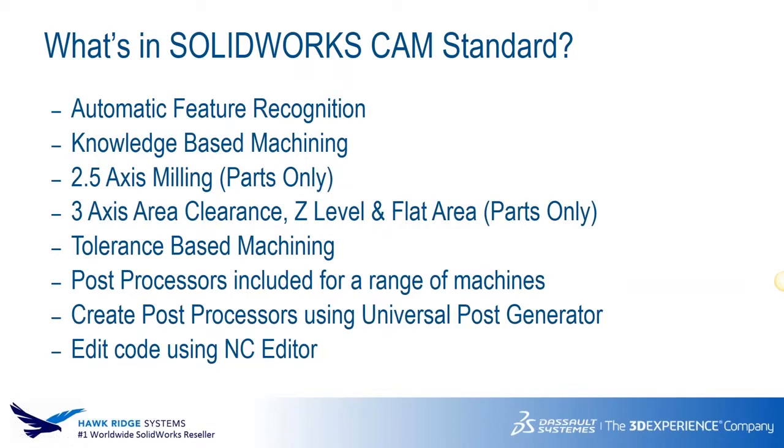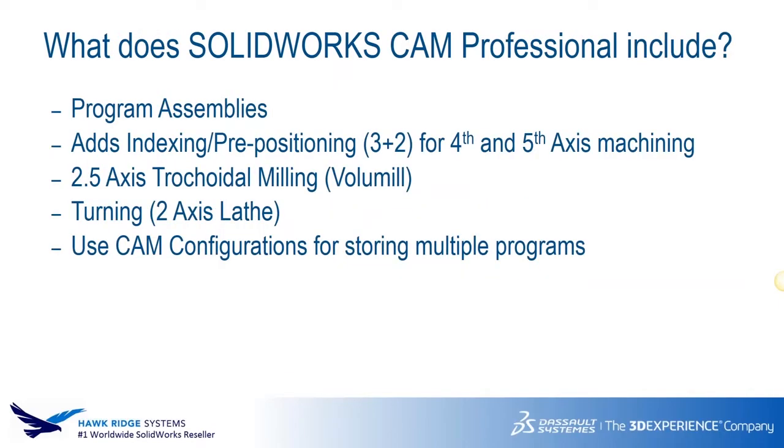strategy. So if you take a simple example of a hole, it might be drilled, it might be drilled and bored, it might be drilled, bored, and then reamed to get it straight. Those tolerances are essentially the practice that those machinists have to go through to determine how accurately that hole gets produced. The software is actually going to do that for you and work with you using the tolerance-based machining. It will automatically pick a boring strategy if you set a tolerance within a certain criteria that you set up.